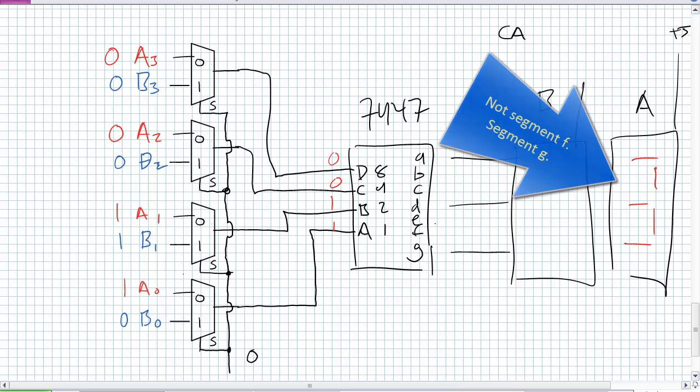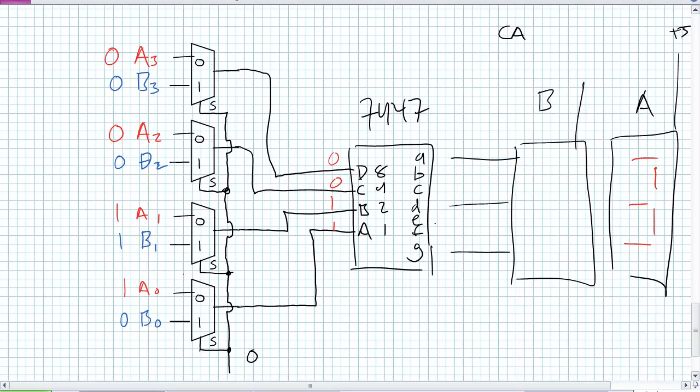Pretty cool. It's display multiplexing. We're probably actually going to go into a bunch of display multiplexing, especially for the use of our FPGA development boards. It uses slightly different methodology, but very similar. All those 7-segment inputs are being sent to every single 7-segment display. It's just that I'm enabling the anode at a specific moment or disabling an anode at a specific moment. And again, you do this fast enough, you should be able to see a display without flicker. You should see the number 23. Pretty cool application of a multiplexer.